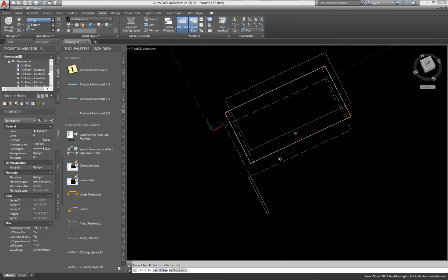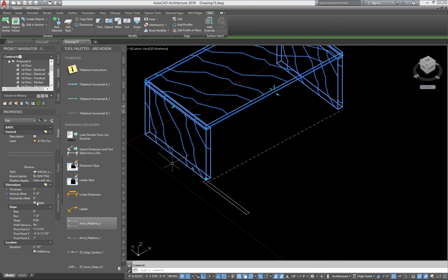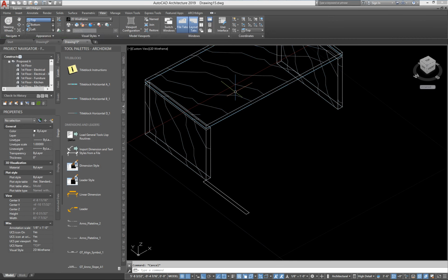All right, so now we can just assign the new edge. So we'll pick that. We'll go over here to edges on the properties palette, and we'll see the 2 that are remaining. Those are the ones we want to keep. Highlight both and set them to, oh, one more thing. I'm jumping too fast. We want to do a slab edge style.